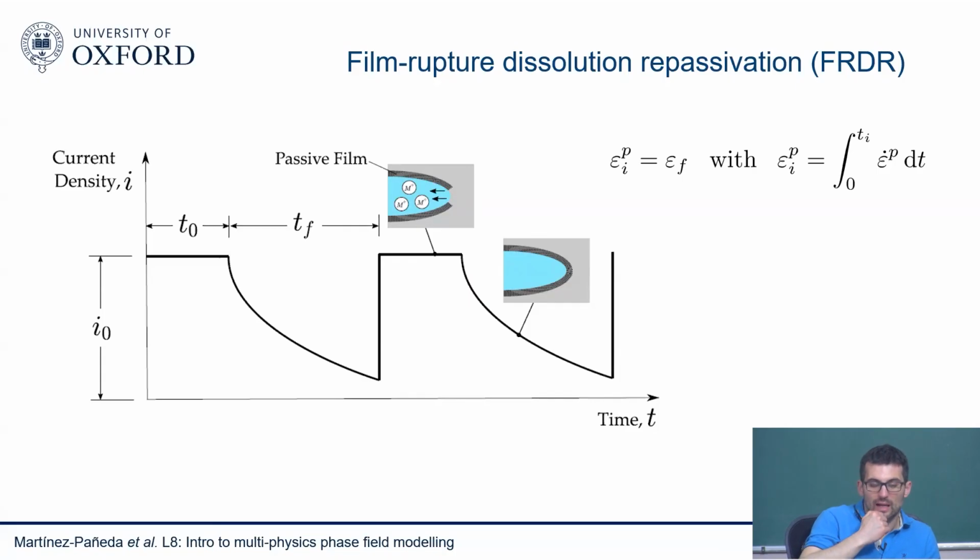And what happens here basically is kind of a cyclic process. So you have your stainless steel, which forms this passivation layer. So let's assume that something disrupts that layer. So your corrosion current density is at a maximum. You have no passive film. You are losing metal significantly. As you start passivating your film, so as your film starts to deposit, then you reduce the corrosion density. Your corrosion process starts to wind down. But then eventually something happens. You rupture again your passive film, and then you get again exposure, and then again you start repassivating.